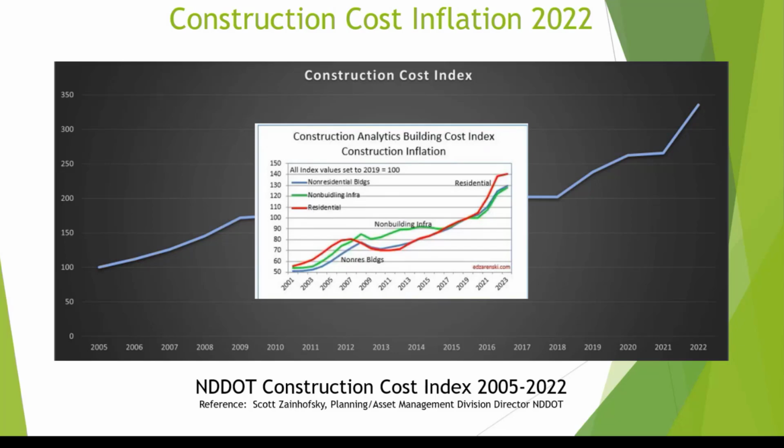with the construction cost index, though, is that more and more you're seeing, in the old days when I started, the cost indexes were basically narrowed to three categories: aggregate or rock, Portland cement, rebar, well, four, I guess, and asphalt pavement or asphalt liquid. And those are becoming a lot smaller percentages of the project cost because you have things like stormwater control. You all know the drill of all the add-ons of construction projects, and they keep eating up a bigger chunk of that total dollar amount.